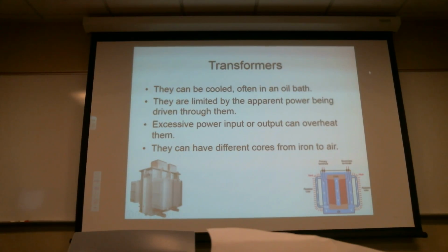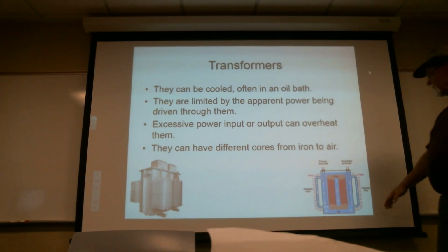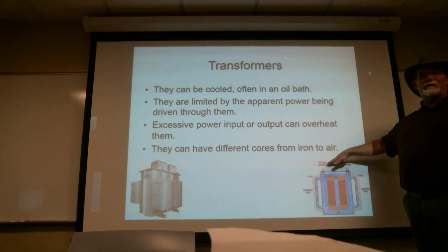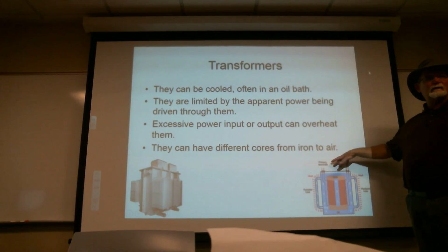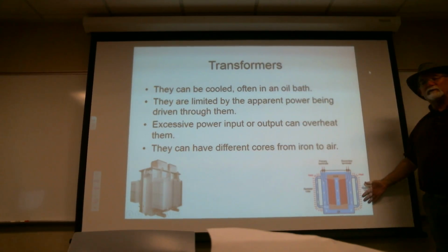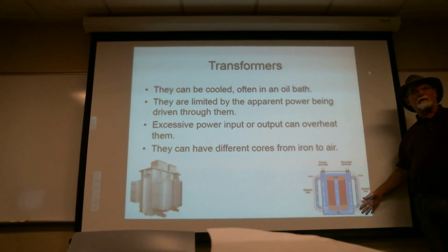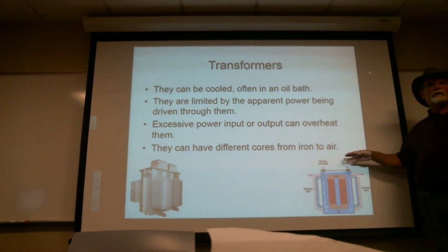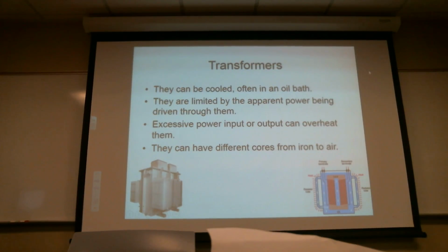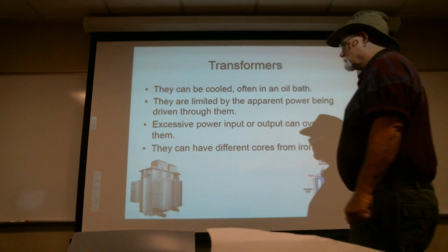They then will have either a pump running it, or more often they design these radiator elements so that as the heat builds up, the oil just starts rising. As it rises, it flows out this way and cools down. As it cools down, it starts sinking. So these just naturally circulate once they start warming up a little bit. Oftentimes they'll put that behind a fence so you can't get to it, or in the big green box, because these things can actually get pretty hot.